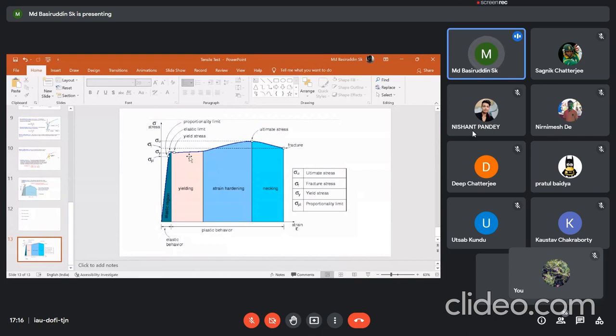So here, what actually happens is that the steels I have mentioned, the low carbon steel or mild steel, contain interstitial alloying elements like carbon and nitrogen. Those are blocking the dislocation motion in a certain way.